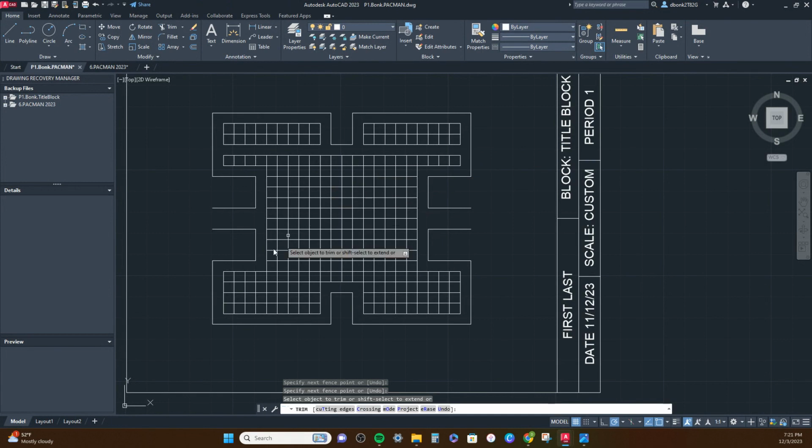I'm going to actually draw this on the other side at the same time. Same on top and bottom of the board. Might as well do these at the same time. Now you're going to count 1, 2, 3 in and draw through the fourth. You can actually go right through that whole corner there. On the other side, 1, 2, 3. Go from the fourth straight through this whole board.